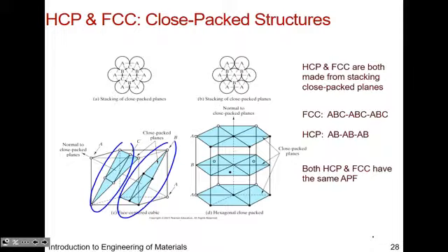And so if you look at the close pack, you see all the A atoms. So in one layer, that's labeled A. The next layer is labeled the B atoms, and then the next layer after that, the third layer, is labeled C. So basically, you can have atoms, and the next layer, you can put them at an interstitial. So if you have 3 atoms on the first layer, there's a hole in the middle, right? So the next layer, the second layer, you can put an atom right there and propagate the same type of symmetry. So that's for FCC, and you do A, B, C, A, B, C. You can stack it in that way.